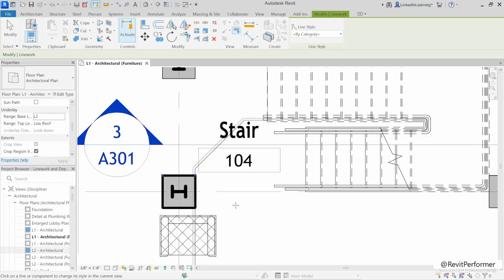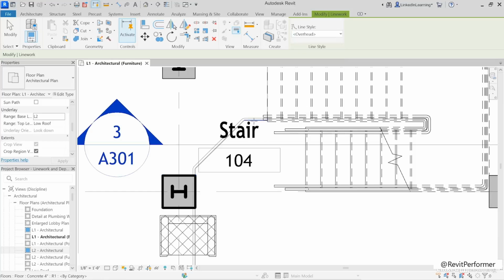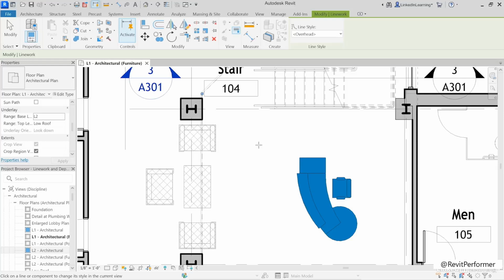Okay, so now that you understand how to use the line work tool, we can apply it to get the effect that we were after, which is to display a dashed line overhead. And it turns out that there's a line type here just for that purpose. It's called Overhead. And I'll click that, and I'll touch this little horizontal line, the diagonal line, and then the vertical line here. And that will, of course, go down the full length of the floor element.